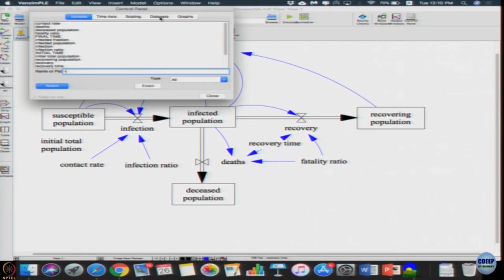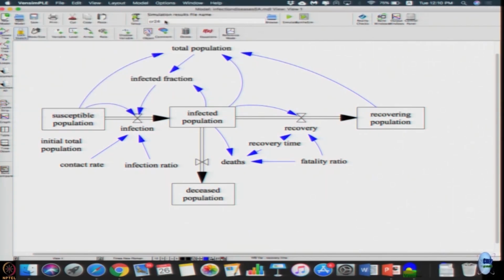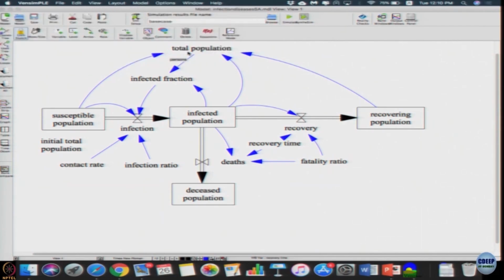If you go to the control panel, data sets, there will be a lot of data sets you might have used in the previous cases. It is best to get rid of all of that, so that we have only the base case. So, first write here the base case, simulate it and keep it ready. That is the base case against which we are going to compare.